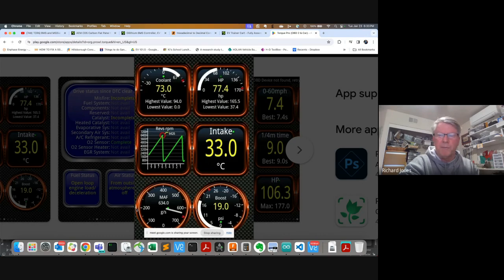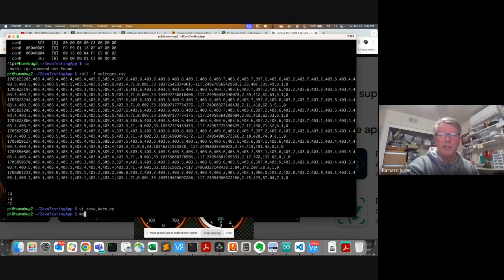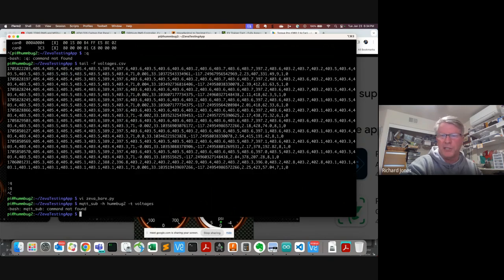You can see the data from your car, but Torque is really geared towards gas cars. And so with EVs, there's this extra work needed to create those custom IDs to show cell voltages and motor controller and so on. There are some folks out there that have basically taken the RPM of your EV motor and have that show on the standard RPM for Torque. But things like cell voltage 27 just don't exist in the standard messages out there. So something has to translate.